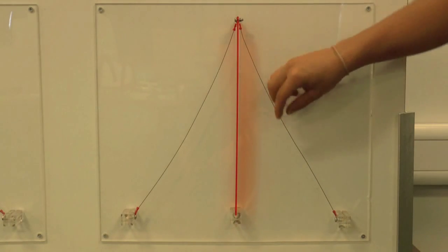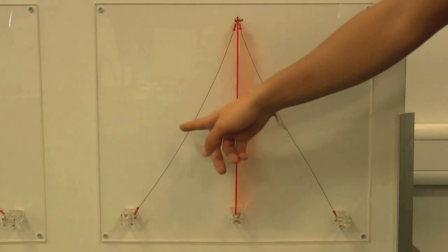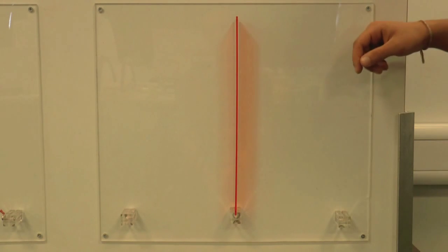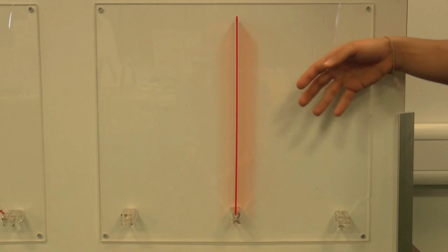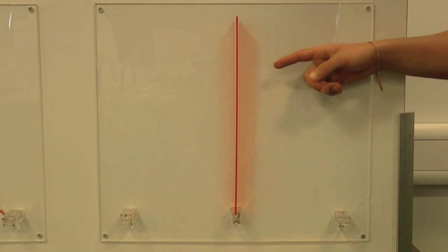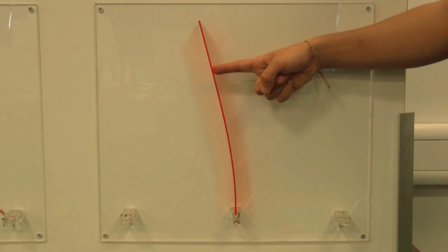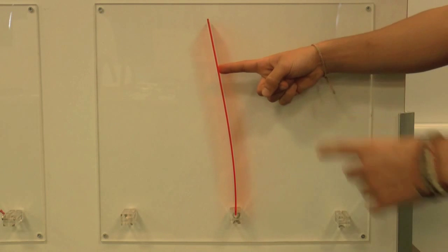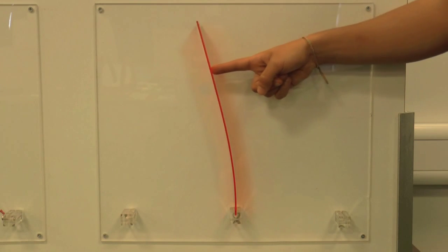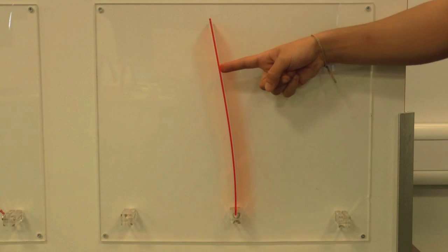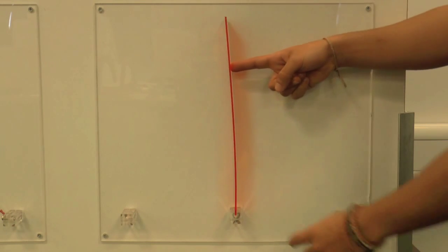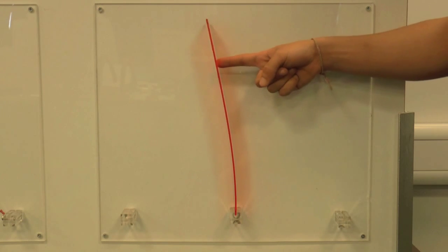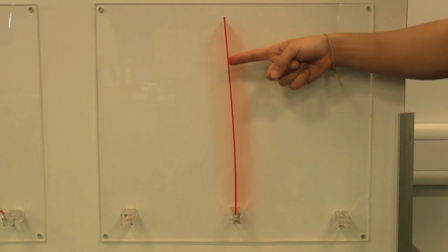To really appreciate this, let's see what happens if we take away the cables. Okay, now that we've removed the cables, let's see what would happen if we applied the same lateral load as before to the mast. For the same lateral load, we notice that the mast deforms a great deal more than when it was restrained by the cables, and thus we can see that the mast behaves exactly as a cantilever would, with one fixed end and one free end, and that kind of beats the point of a mast where we need it to be rigid to resist the wind loads.